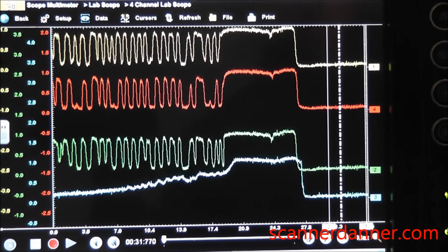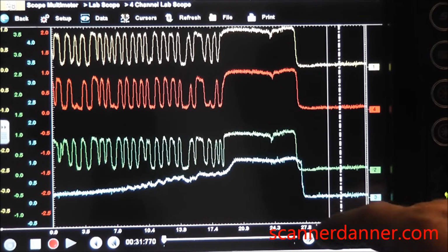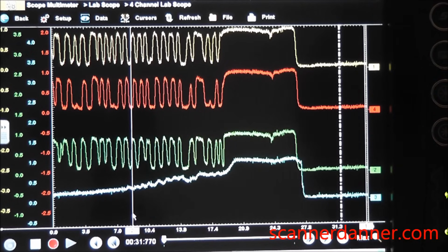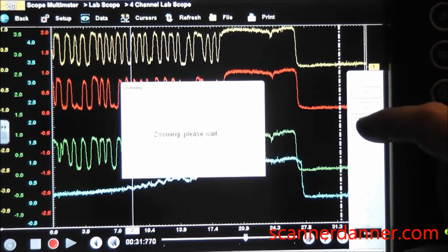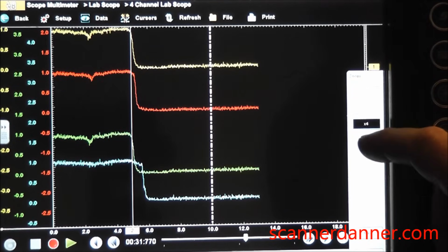And of course you can go on IATN and read about a lot of the cat issues, and I'm sure there's a ton of other variables, anywhere from reprograms to issues with oxygen sensors and things like that. But I just make sure myself that the O2s are switching, that they're switching fast. And I don't know if we can really show too much of that. I don't see what our switch rate is here on our upstream O2, the frequency number.